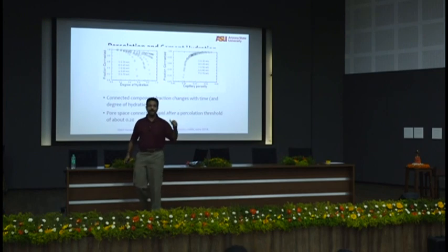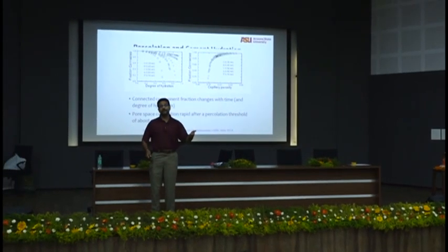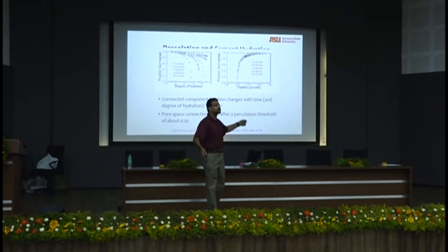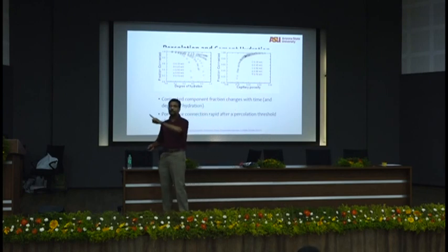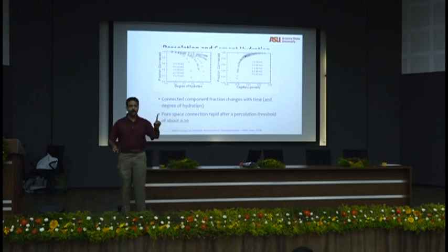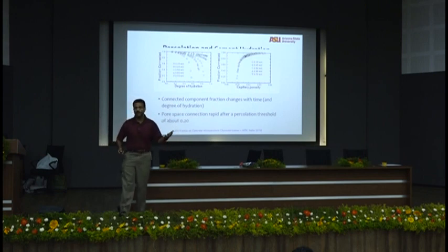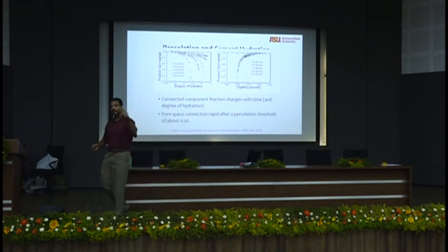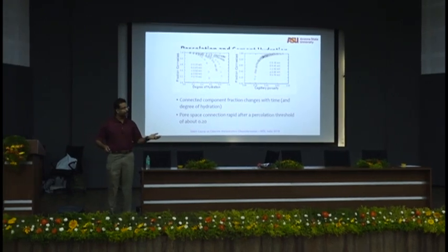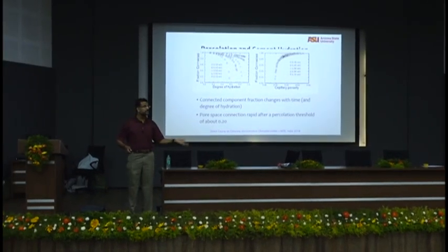But you do not want, like I said, to be looking for an 85% degree of hydration to get to that point, because 85% degree of hydration is going to be an unattainable thing in general, unless you make a bridge deck and pond that bridge deck for 1 year. Not let the traffic go through, put a dike on that, fill it with water for 1 year, then you get 85% hydration. If you cure for 7 days, forget 85% hydration. You're going to get 50-60% hydration at the most. And with that 50-60% hydration, if you already have a higher water cement ratio, you are ending up with a very, very high chance of durability loss very quickly.